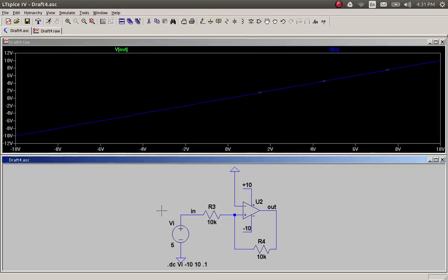So I get a really strange waveform, input as output. Well, that's not possible. Yes, so the reason is I have marked plus minus 10 volts but I haven't put a voltage. So let's do that. So notice, just because you call a node plus 10 and minus 10 doesn't automatically make it plus 10 volts and minus 10 volts. You have to add voltage sources that are plus and minus 10 volts.